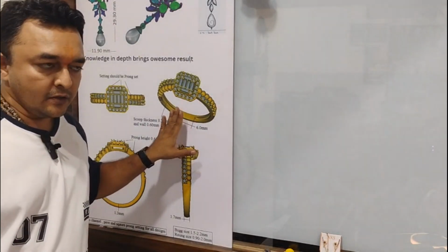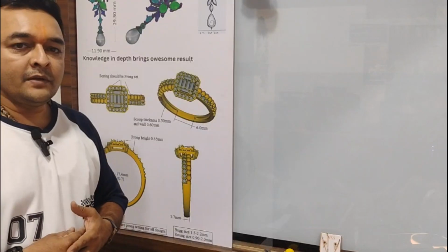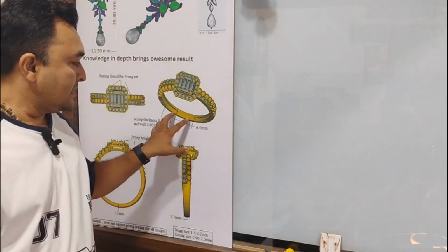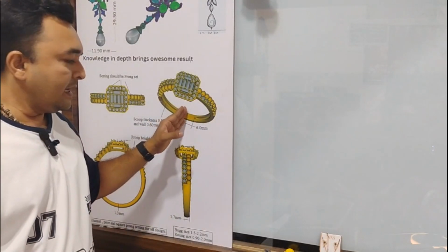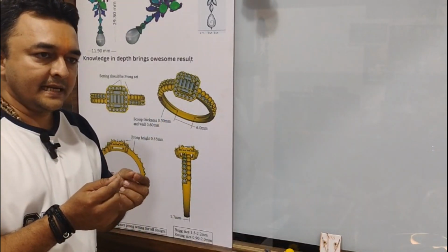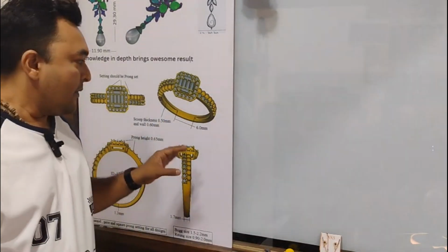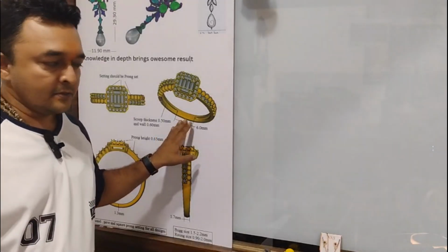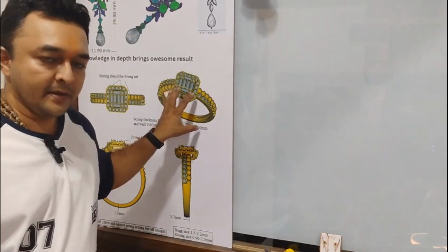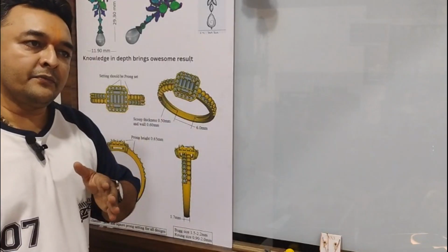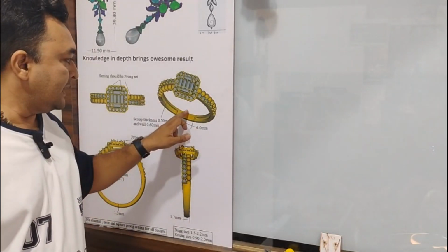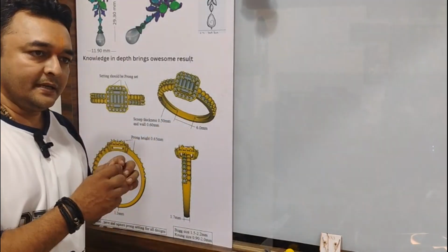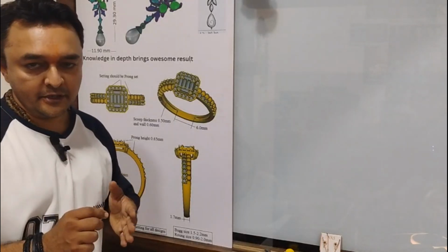material as it is, because when we need to resize our ring model, this is the only portion which can be cut, and you can extend it and add extra material when there is a change in ring size. So suppose you have created USA size 7 and you require USA size 11, they will cut out this portion, add some extra material, and they will solder it and finish it.